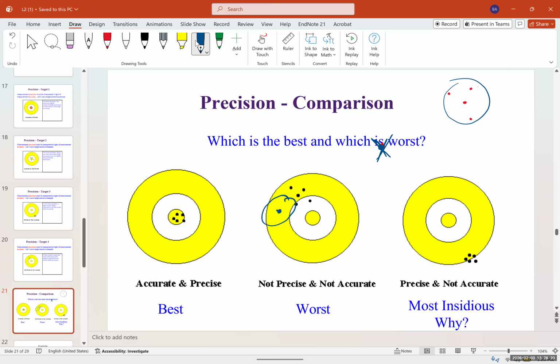And the same thing for measurement as well. You want to be accurate and precise, but if you're not accurate but you're very precise, it's easy to correct that. One example I can give you is measuring voltage. If your voltmeter has an error, what we call a drift, of 2 volts, you can measure all your voltages and then finally add 2 volts to it or subtract 2 volts from it.